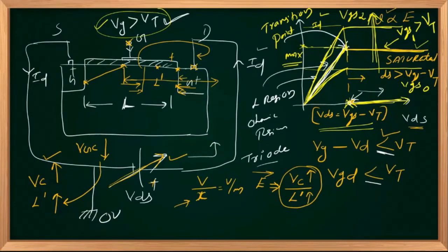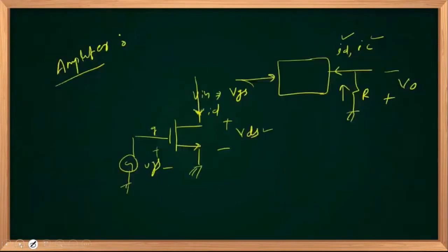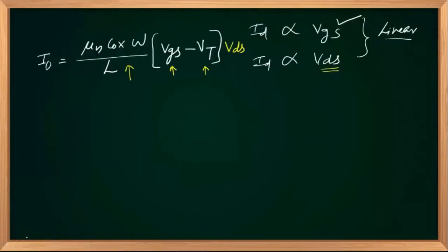One curve is for one particular VGS, right? So all parameters here are constants except VDS. So ID equals a constant times VDS, ID equals K times X, because VDS is on the X axis. So that is the equation for drain current in the linear region.